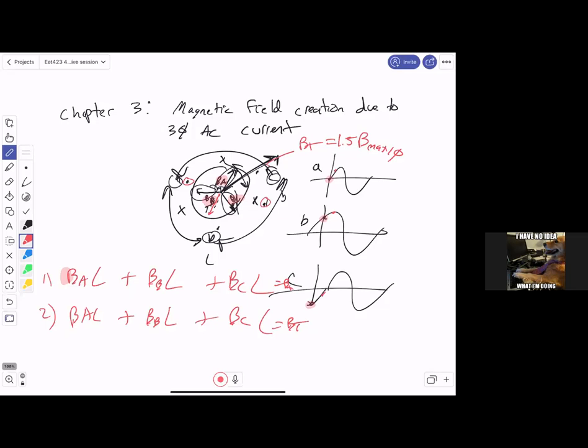So essentially, you can extend this to a single-phase motor, where you've got a single phase, and all you do is run a capacitor in the circuit so that you get a 90-degree phase shift between the phase that you have and the second phase. By introducing that second phase, you get this rotating vector that goes around, and that's essentially how a single-phase motor works. So the questions could be, what's the rotation, positive or negative, for a three-phase motor?